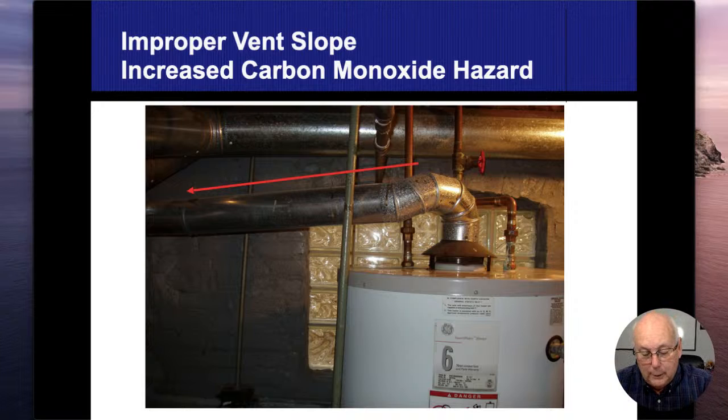When it comes to water heaters, when we look down at these escutcheon plates, which are pieces of plastic where the water pipes come into the water tank, they melt pretty quick and easy. So if I'm backdrafting, or if I have backdrafted at any time, I'm going to see those things melted.